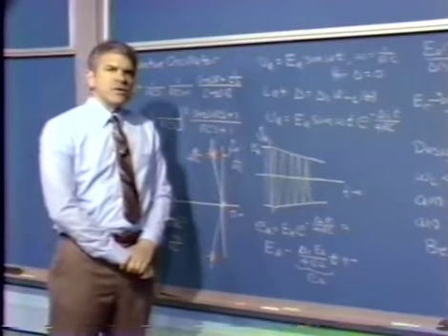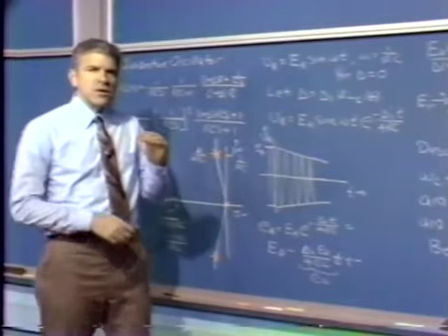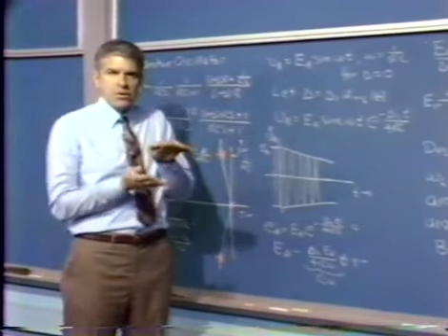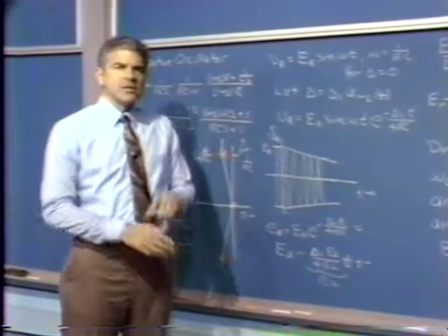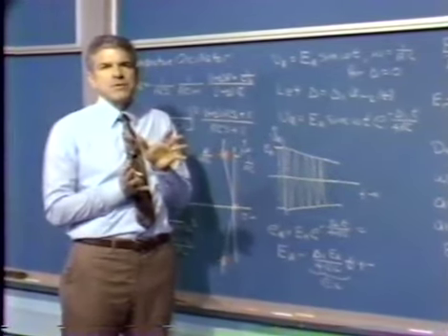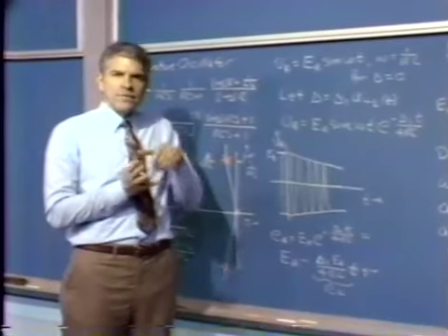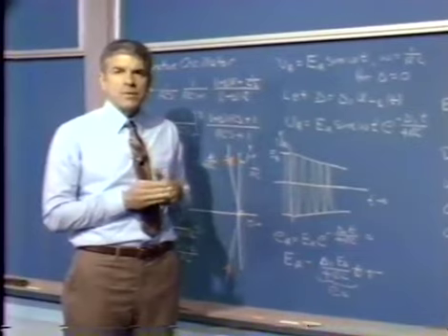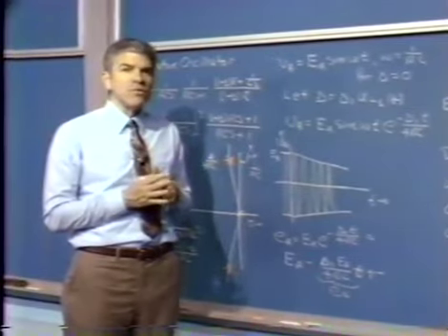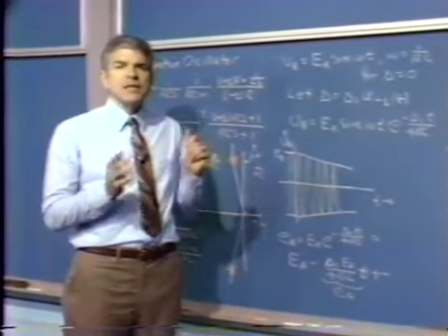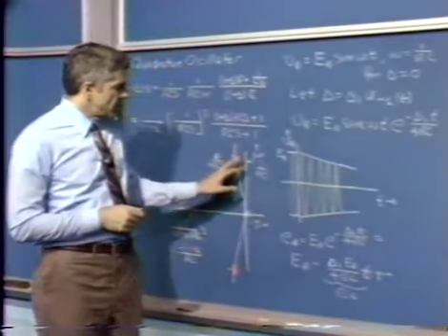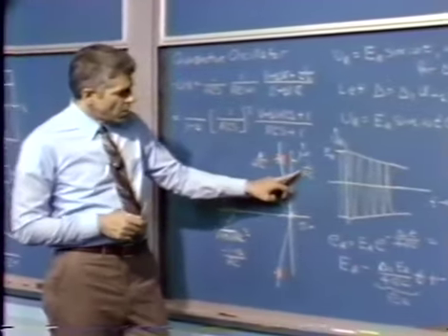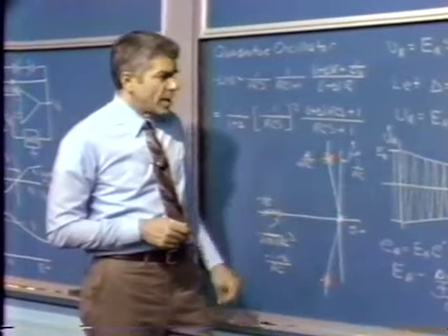What we're really going to do here is build a very, very slow loop that controls the amplitude of the output signal. And there's sort of 2 independent feedback processes going on at once. One of them is the double integrator loop that crosses over at a fairly high frequency, at a frequency omega equals 1 over RC, and that's the basic oscillator. We're oscillating basically at a frequency 1 over RC radians per second.